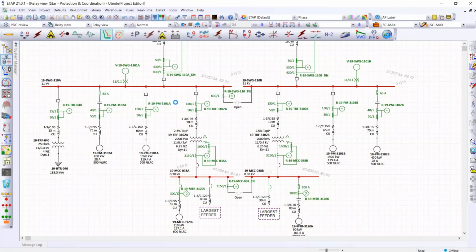So we are not going to modify the data of the motor, transformer, equipment, and so on, but the target here is to modify the settings of some protection, adjust those settings, so we can still have the older version of protection relay coordination studies and settings, and we can have the new version of relay coordination settings. That's the main purpose of revisions, which perfectly matches my target especially.